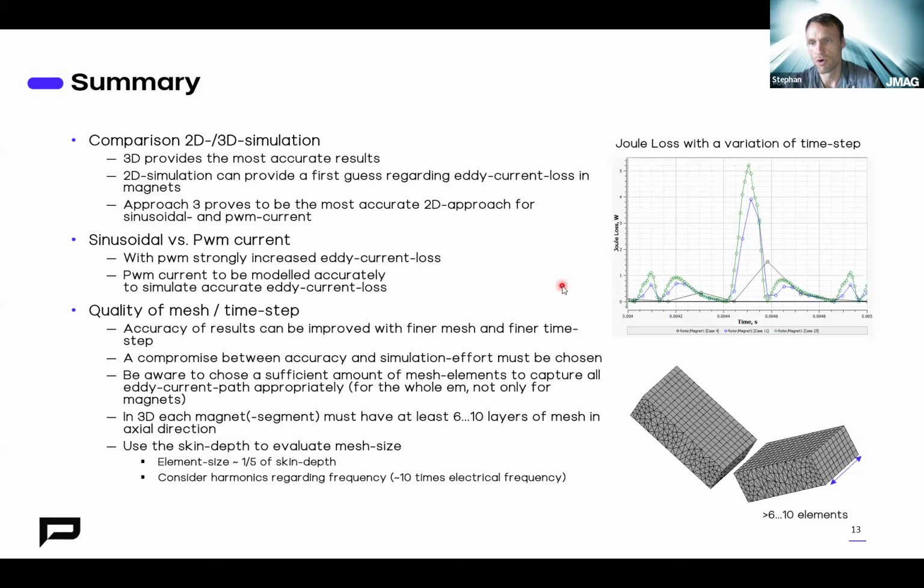But as already most of you do, at least as a final simulation, it's really recommended to do 3D simulation to take into account the eddy current loss of the magnets. For the 2D approaches, I think approach 3 proves to be the best approach to consider the eddy current loss in magnets for all supplies, so for sinusoidal current supply and for PWM current supply.